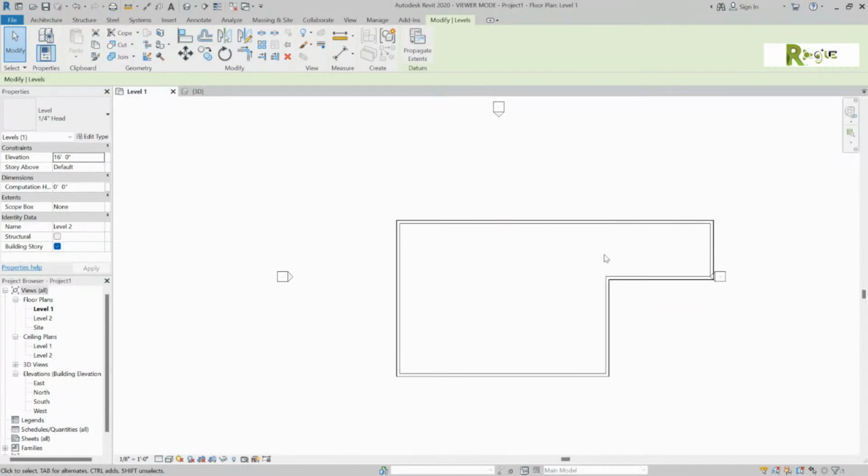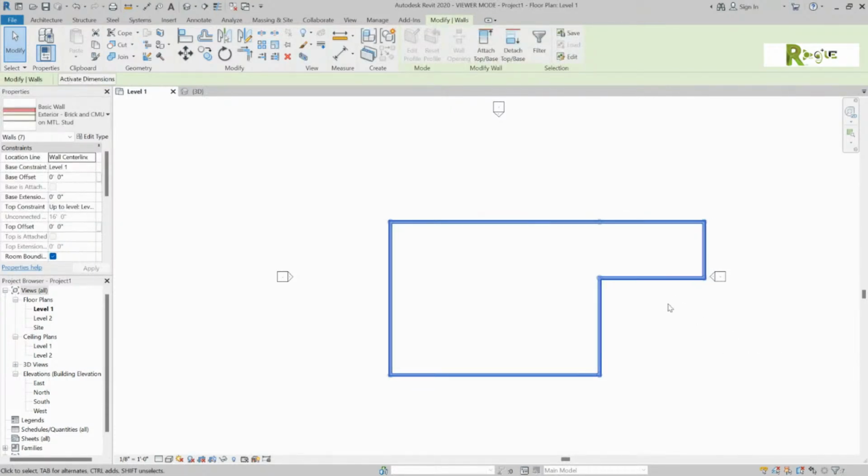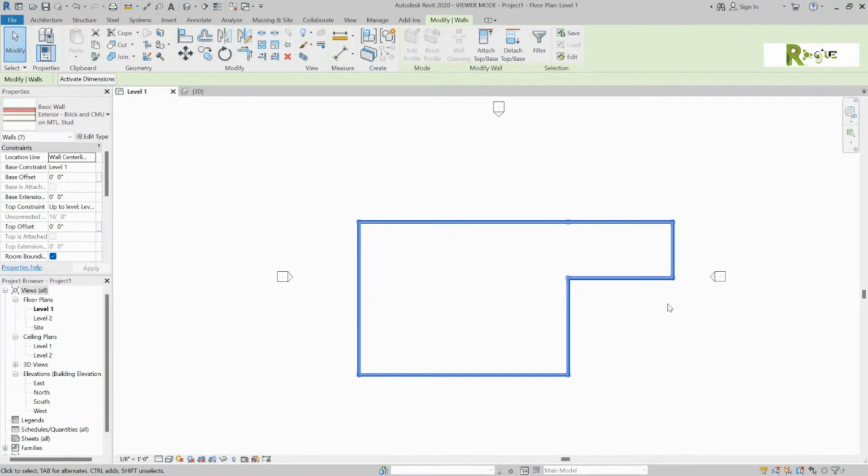So this might be a good time, if you're early in setting this up, to slide that whole building over a little bit so it's centered well through those elevations. I like that. And if you hold the shift button when you use the arrow, it's like a turbo nudge. You see how it jumps bigger? And if you don't have shift, then it's a little step. And that's all related to how far you're zoomed in.